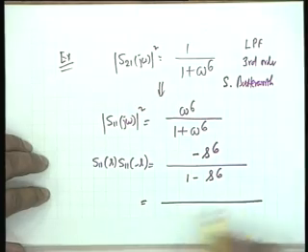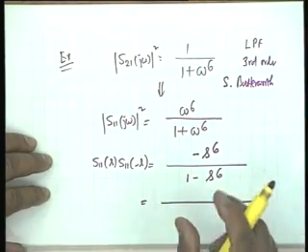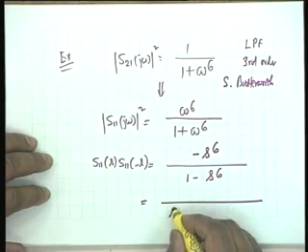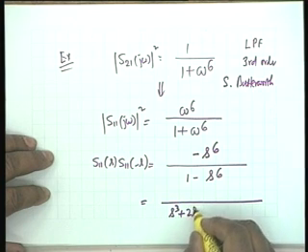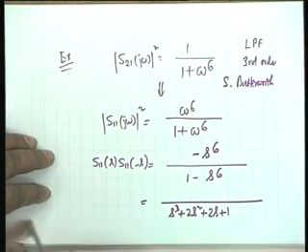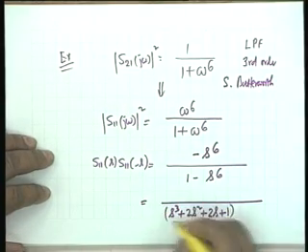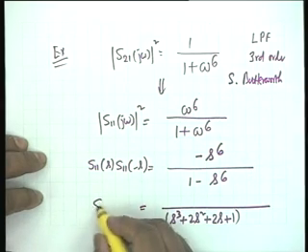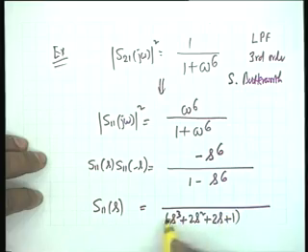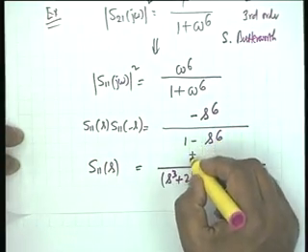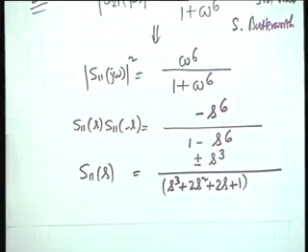The denominator, as you saw, was 1 plus s multiplied by 1 plus s squared, which gives you s cubed plus 2s squared plus 2s plus 1, I hope I am right, and minus s cubed plus 2s squared minus 2s plus 1. So, let us find out only S11(s). We take this as the denominator. In the numerator now we have a choice. It is either plus s cubed or minus s cubed. We shall take both of them and see what the network is.